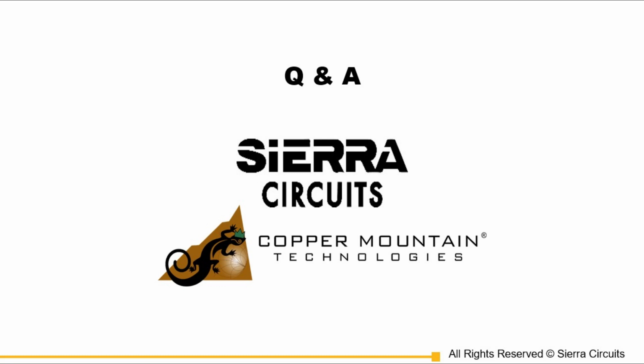I'll go ahead and take the 300 hertz question. It looks like James underneath answered the question. It's all about the wavelength. At 300 hertz, you would be concerned if the transmission line is a quarter mile long or something. Actually, the wavelength will be so large. So 300 hertz is basically DC. It is DC, yeah, for all practical purposes.